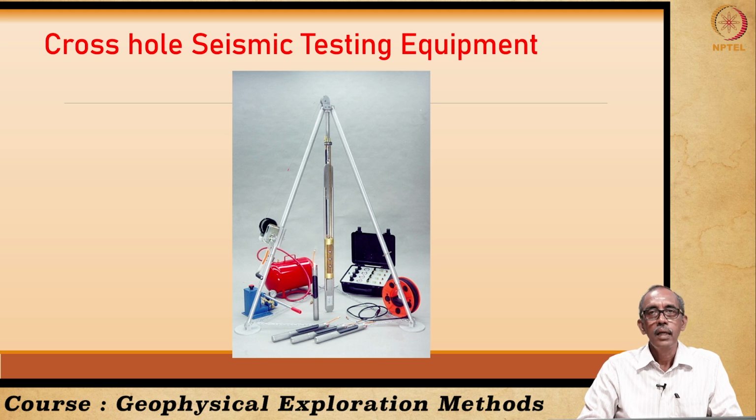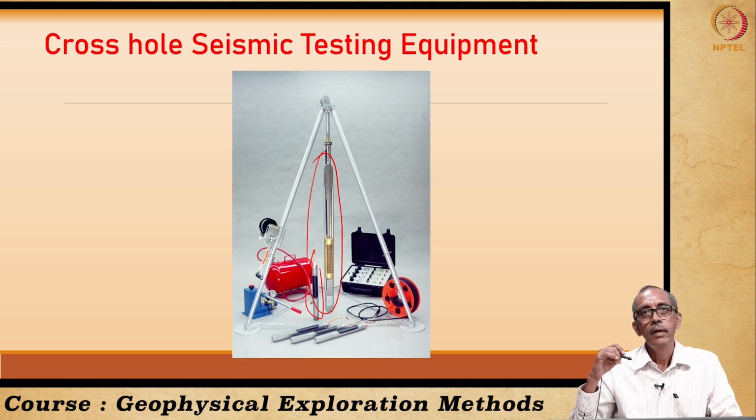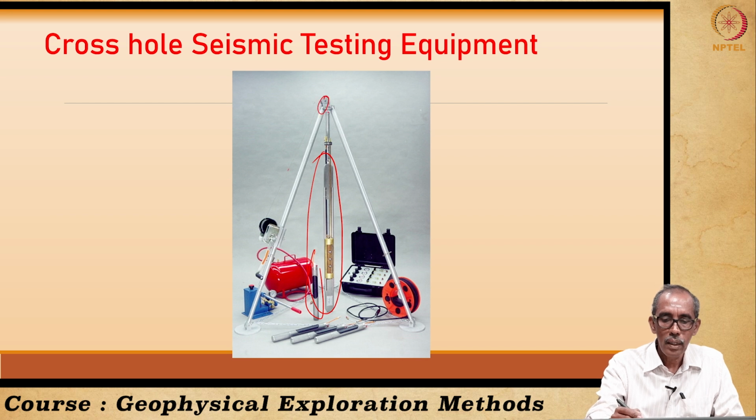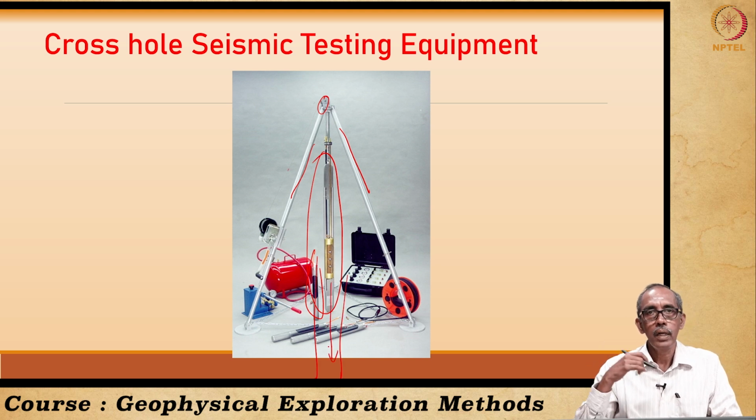And what are all the instruments that are necessary to conduct the seismic cross-hole test? We need a source and a geophone. A source and a geophone are necessary. However, we also need some additional facilities such as a pulley and a tripod system. This will be kept over the borehole and the tool will be lowered slowly into the borehole.